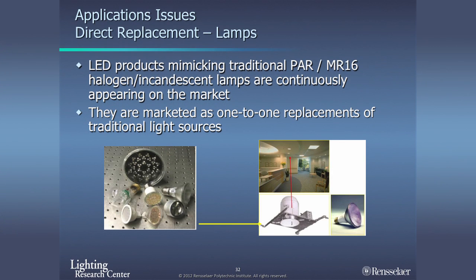This is an IC rated fixture, which is typically used in residential or any ceiling that has insulation. Now, if I stick this LED with all of its thermal components behind it into this metal box, where's the heat going to go? Nowhere. It's going to stay in that metal box, and it's going to heat up, and heat up, and heat up. And this LED that was rated to last 30 or 40,000 hours is going to last about half that time.